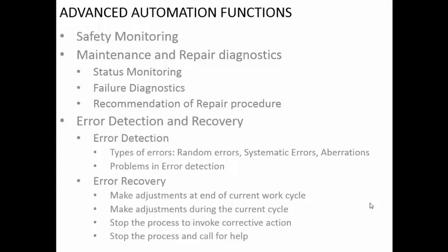In the case of status monitoring, with all this data, it may be possible to predict an incoming failure. Maybe you are continuously detecting a lot of vibrations in the spindle motor. Based on experience, it is possible to know that maybe the bearings are worn out. So time has to be allocated for replacement of the bearings. Maybe you will inform the planning people to ensure that the machine is left out of production for 2 hours or 3 hours. You replace the bearing and the machine will be back in operation.